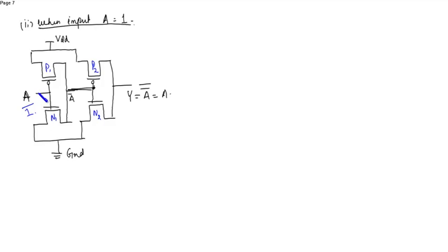When A is equal to 1, then N1 will turn on and P1 will turn off. P1 gets open circuited. N1 gets short circuited.